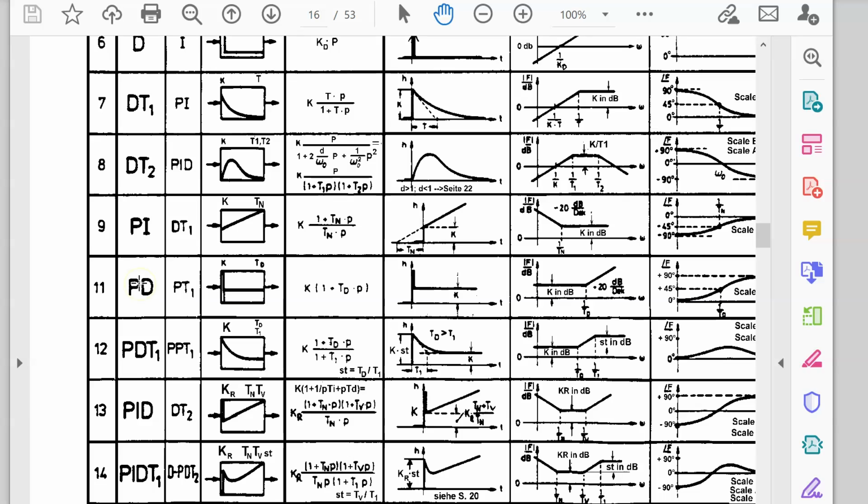In the student paper some years ago, I also added the PD part, but I cancelled it because this is just a theoretical idea: can a PD accelerate a closed loop system? Of course it can, but you cannot build it because a realistic PD is not possible.